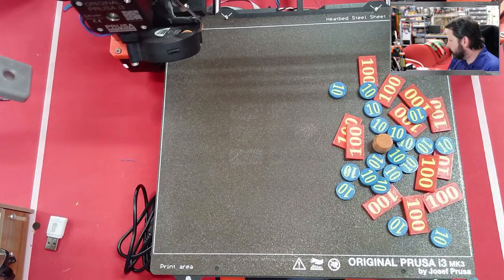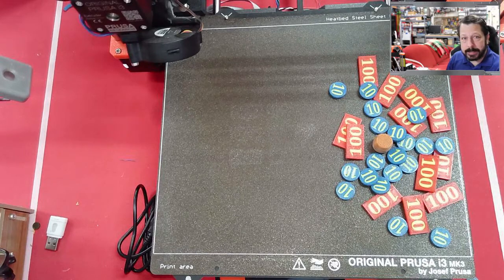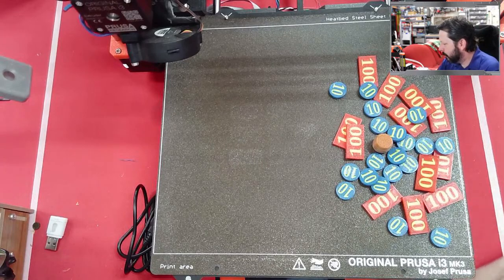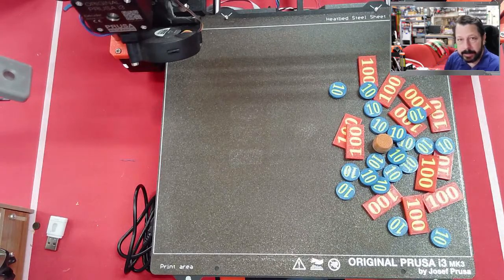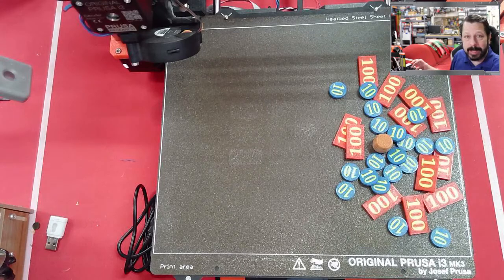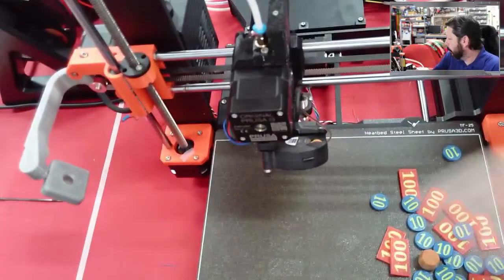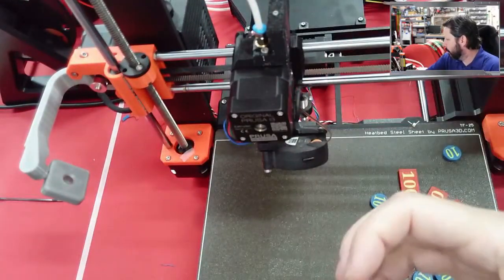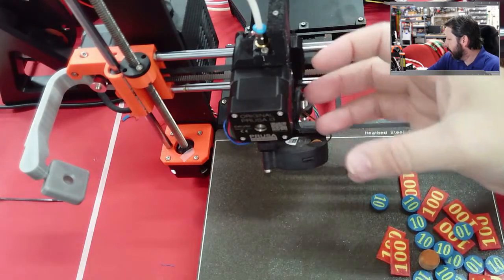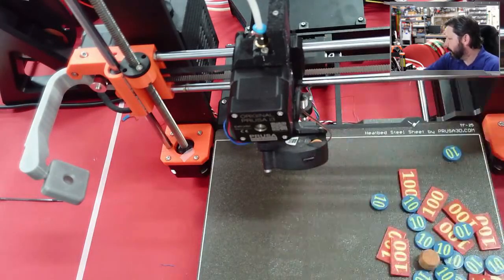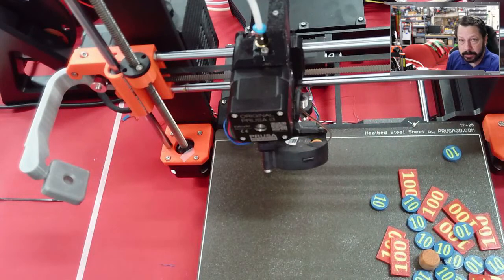There are other types. There are tool changers. I do not have a tool changer printer. They're pretty expensive. Maybe someday I'll manage to get one of those, but basically it goes in and there might be 4 or 5 tools or nozzles at the back, each with its own color, and your carriage is really just a holder for different tools, and it goes and picks up a tool that it wants to print with and snaps it on and prints for a while and puts that tool back and gets another tool to print a different color or a different material. Those don't have as much waste.